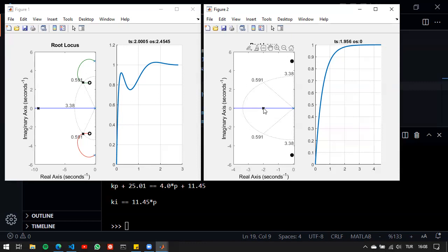Now, we're not actually using a PID controller, or we're not using some other type of feedback loop on top of a feedback loop. What we do is we just use the PID controller as a base, but we decide that we need another pole in order to have some j omega values in the closed loop. Therefore, we add another pole. And since these pole and zero cancellations are exact in our case, we're choosing them exactly on top of the poles, then the only thing that is left is to decide on the gain that gives us the given zeta and omega and intersection point.